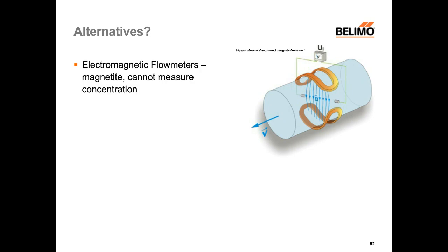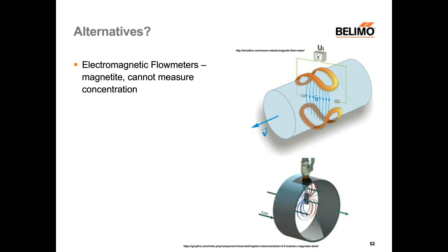There are also electromagnetic insertion sensors. If they are not sold with a pipe piece, but only inserted in a common pipe anywhere, they measure only the flow velocity at one point. And the influence of the flow situation is not addressed at all. So this results in a very, very poor accuracy on volumetric flow, even if they state a good accuracy on the flow velocity.